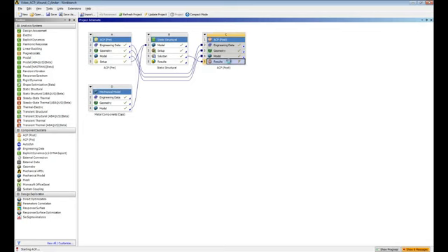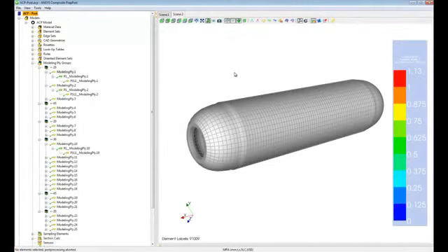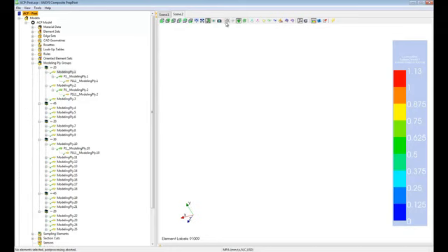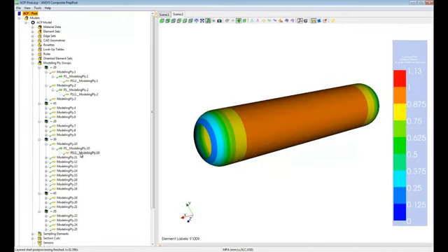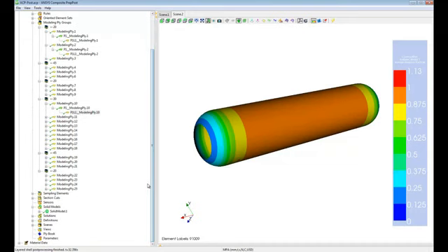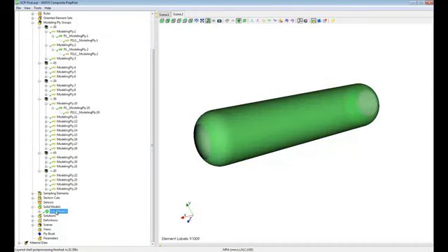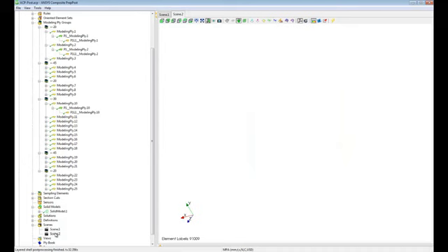We could look at the standard results like deformation and stresses, but let's concentrate here on the failure of the composites. So here is our composites model again, and we have just removed the caps to work only on the composites part. So what we see here is a ply-wise result, so we can look at each and every ply and look at a scalar value called inverse reserve factor that tells us where the critical areas are. When it's above 1, that's a danger area that may fail, but at this stage we don't know which ply or for which reason this is going to fail.